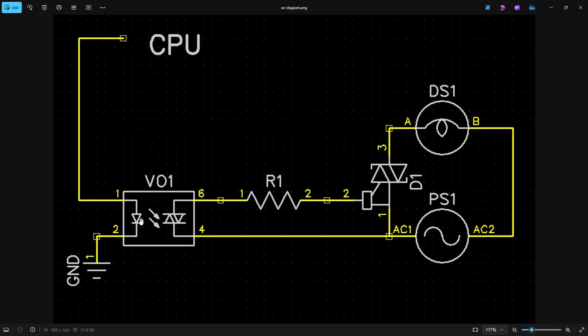So basically, it's like hooking an LED up. If you were using an Arduino, it's no different than having an LED on an Arduino and controlling it. But when you control the LED, you're actually controlling the turn on of a Triac. So this is the circuit and how it works. As soon as you turn on the LED here, it sends a voltage to the Triac, isolated, many thousands of volts typically, so that all your low voltage stuff is safe and protected from the high voltages. Feeds it in to turn on the Triac. Current now flows through the circuit and the light turns on.